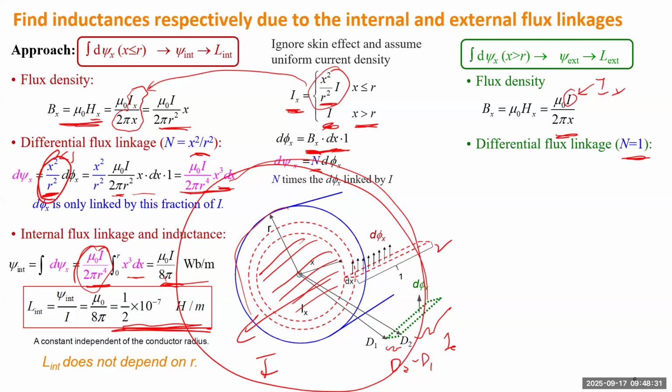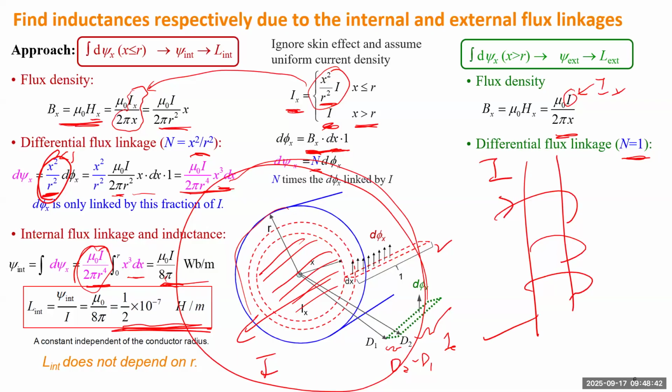Does everyone follow this? That's the only difference between the two sides, right? Let me explain this one again. Think about a transformer. This is current I, right? There's N equal to 3. So if the flux inside this leg is phi, the flux linkage is basically just 3 phi. Is this clear?